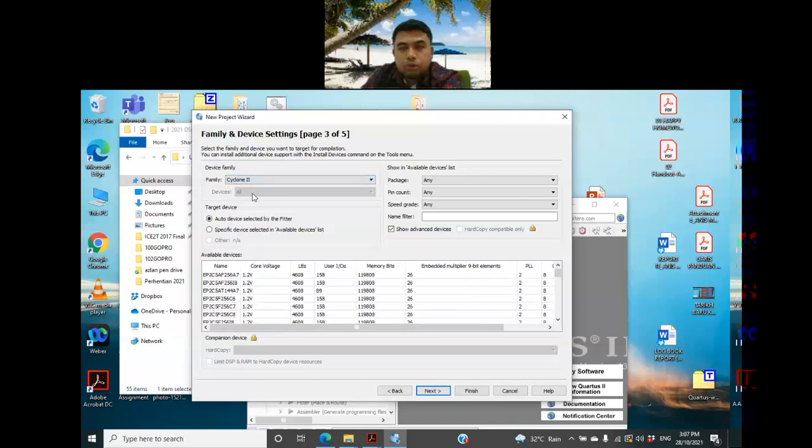Okay, Cyclone 2 board. For Cyclone 2, you can choose any suitable device. For example, I choose the first one. So for the Cyclone 2 specific device, I choose the first one. But you need to check the name of the board. For example, this board I choose EP2C5F256A7. In the hardware box, they will give you the name.